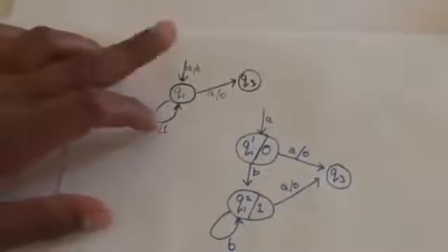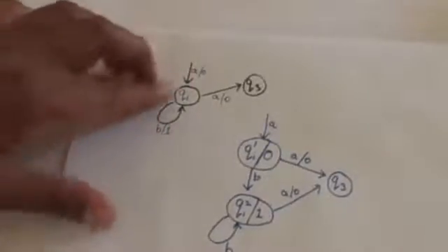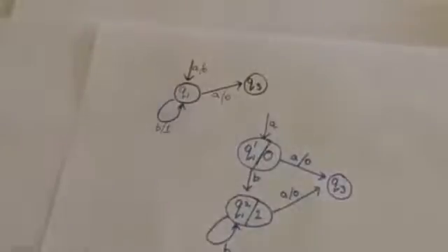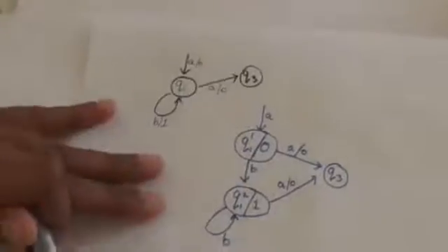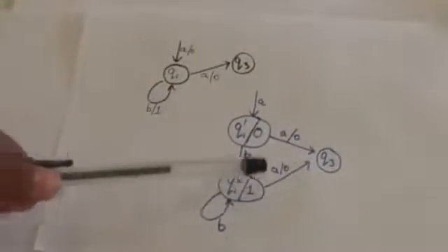So we can say it has 2 incoming edges. One is labeled by output symbol 0 and the other is labeled by output symbol 1. So when we transform it into a state of the Moore machine, we will make 2 copies of this state. With one we will associate output symbol 0 and with the other one we will associate output symbol 1.